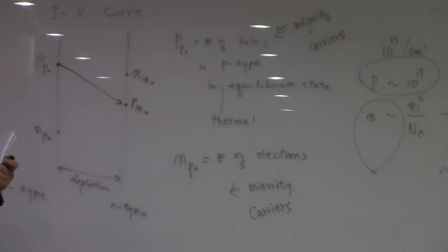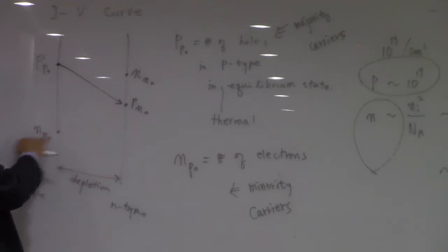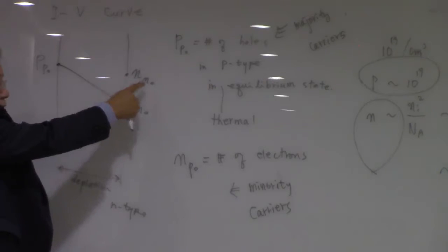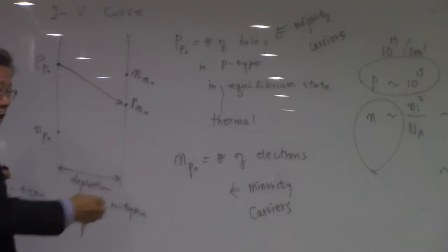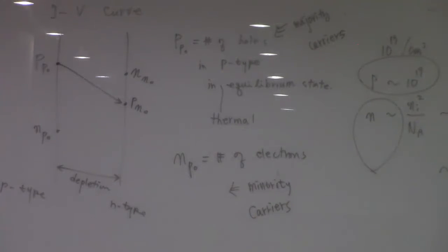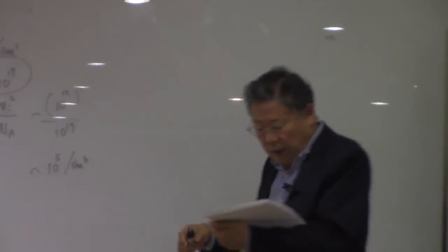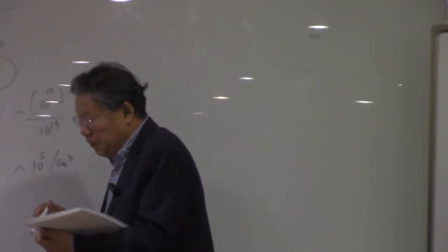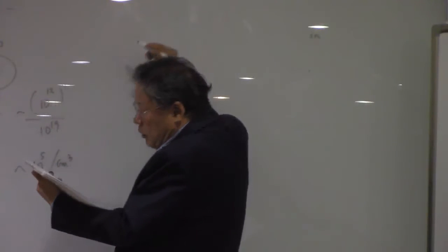And the number of electrons, which is this low, is going to change to this large number across the junctions. It has to. So that huge difference in the carriers forms the built-in potentials, band bending in this structure.